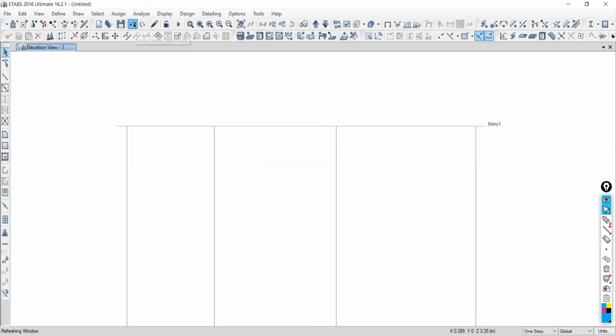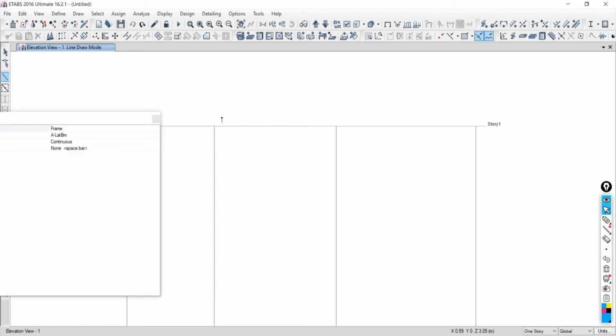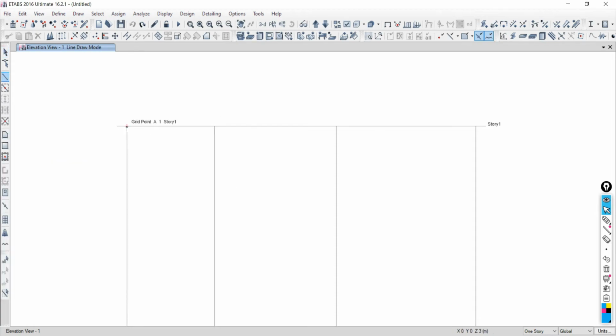That's why what I'm going to do, I'm going to model it. The frame, close this. The first point, move to this joint, move to this joint, then move to this joint. Now let's try to select the joint. Drag from left to right. So joint is selected, right? Drag from left to right. The joint is selected. Now it's okay. Now we can apply that load, okay? See, this joint is selected, so you can assign the load.